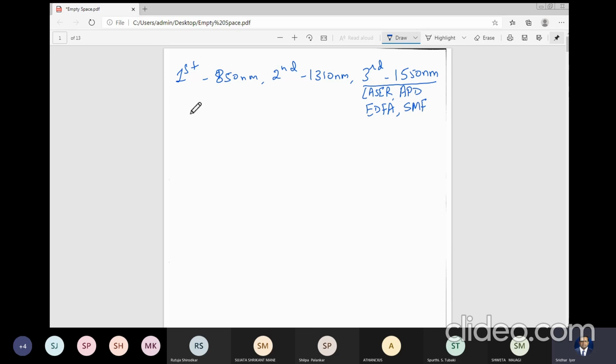So as the source for the system, I need a device which will convert these electrons into corresponding photons. And likewise, on the opposite end, that is the receiver, this should be able to convert light, that is photons, into corresponding electrons, right? So as the source, you could use an LED or a laser. As the receiver, you could use a PIN diode or an avalanche photodiode. And we will be doing these things in module 3.